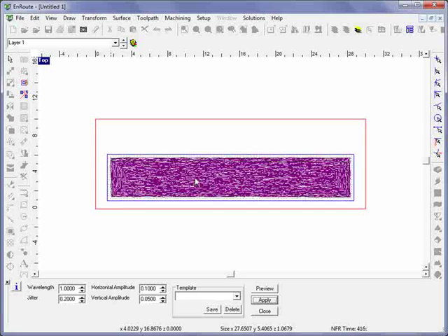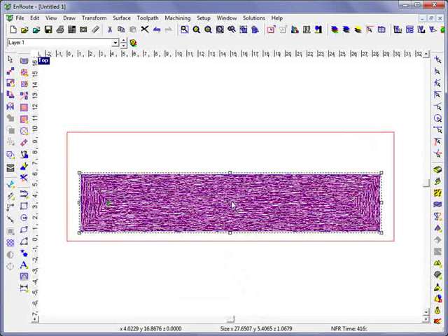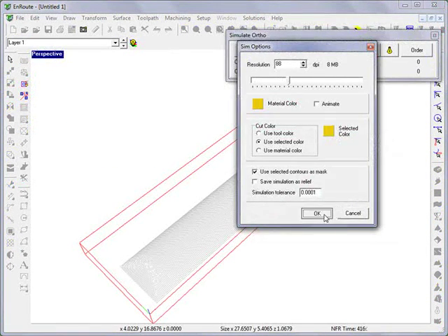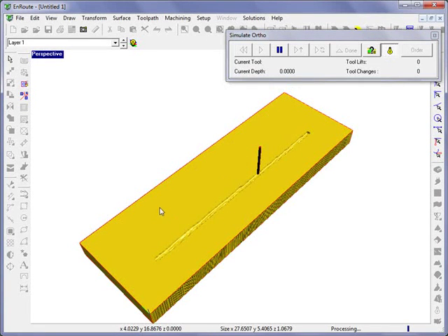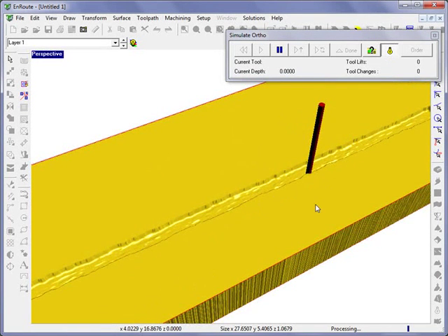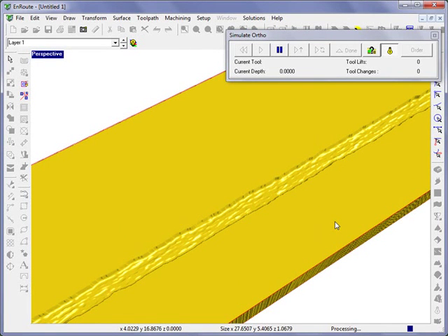So by doing this, we're actually taking what was a pretty uniform toolpath before, and now let's do a little rendering on this one, and we should be able to notice that the toolpath here will show a little bit of a random movement, and this is going to introduce this same type of a random texture into the surface because we're actually creating a texture with our normal 2D toolpath.